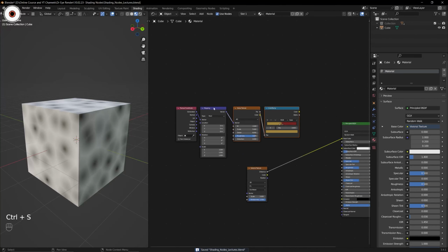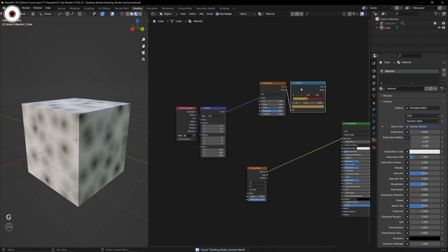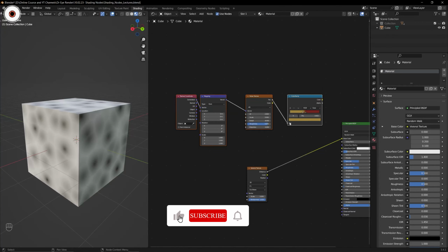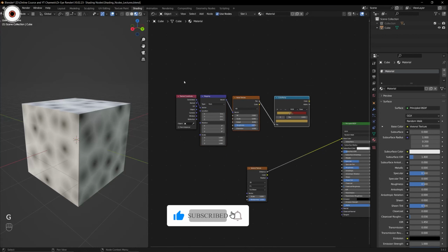How do I align these in the same line? You can also do that. Select all, right? Press S on your keyboard, then Y and 0, right? That will scale them.